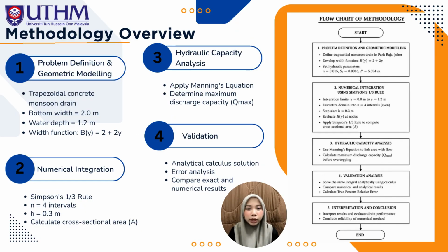The methodology of this project consists of four main stages. First, we define the geometry of the proposed trapezoidal concrete monsoon drain and develop the width function b equals 2 plus 2y to represent the variation of channel width with water depth.